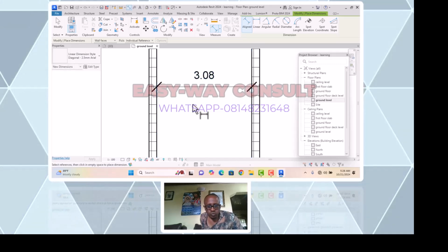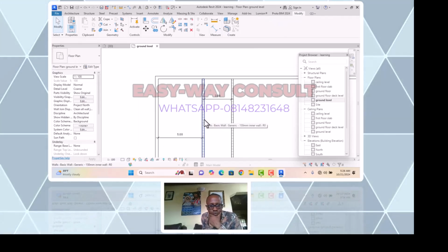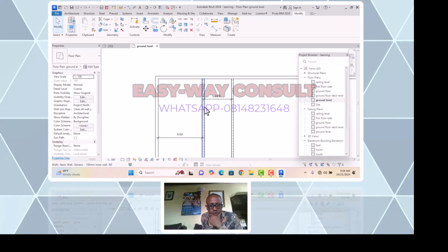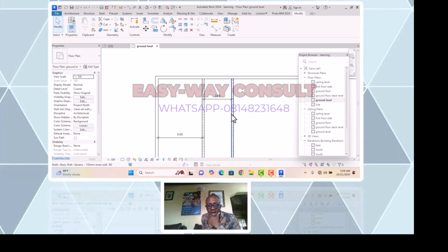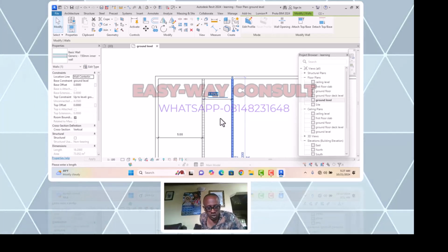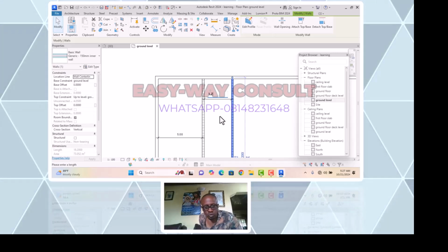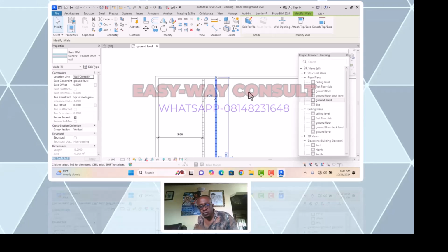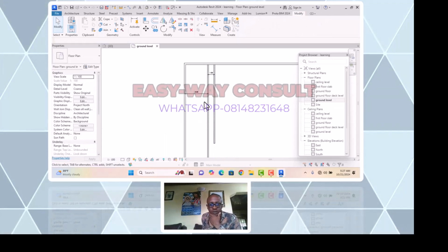Maybe you have seen that it is too much. You won't go here. If you go here to click this wall to change this dimension, it means you are shifting this wall. So you go to the last wall you have created. Go to this dimension. Shift it. Let's assume it is 1.2 that you want the passage to be. You click 1.2. You see, you have gotten it.